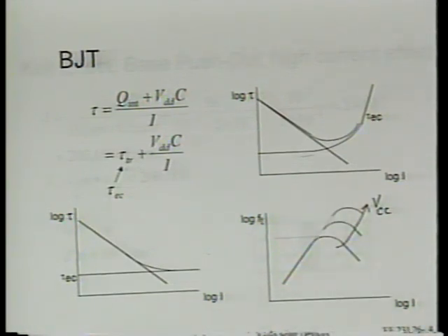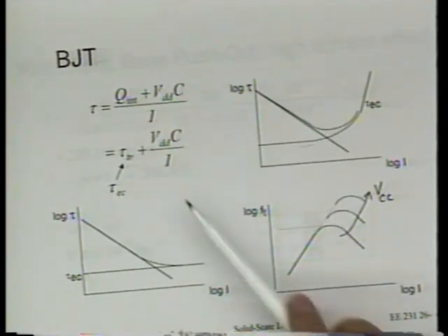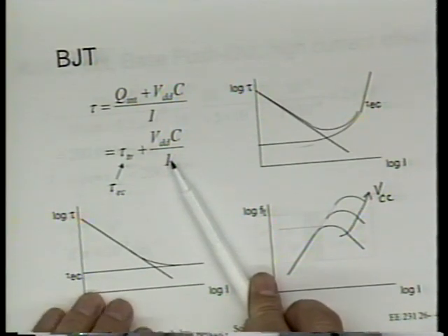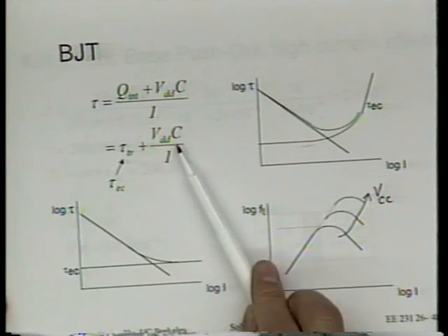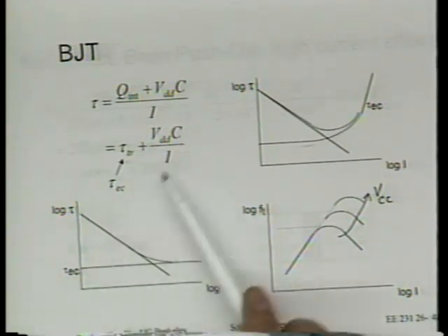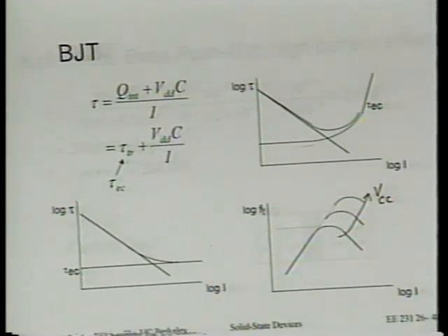This is the remaining thing. What determines the peak operation frequency of the transistor is this new phenomenon we have not talked about. The rising part is the result of this term. It's quite easy. Any junction capacitance, anything you can describe as capacitance, the charge is in here. It doesn't have to be interconnect, by the way. It can be just the junction capacitance. There will be plenty of those, of course.